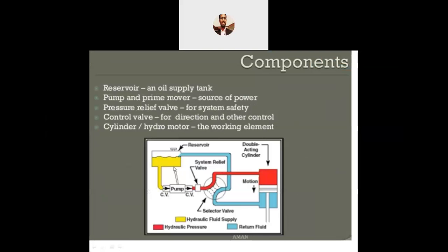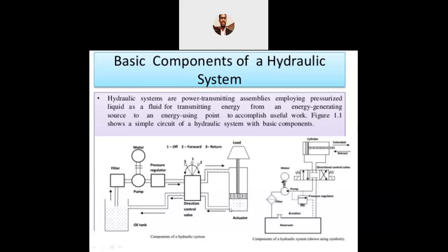When the oil is going through all this, there may be some possibility of contaminants. The contaminants may be of different types. One may be dust particles because of leakage. Second may be minute metal particles which come across during friction. Even with engine oil, whether in a two-wheeler or a four-wheeler, after a few kilometers the color and the thickness of the oil changes.